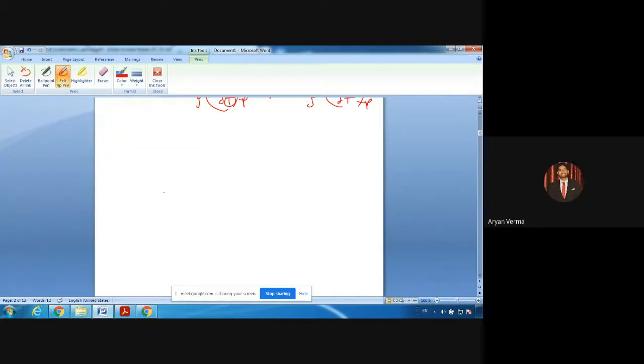सर, जब एक पाइप में आपका फ्लूइड फ्लो करता है तो जो शेयरिंग स्ट्रेस होता... Forget about the pipe. Forget about it. This is the development of the velocity. Yes, sir. If velocity is uniform throughout, meaning the same, no shear force, nothing, no hindrance at all, you will not find any boundary layer. Any layer will be developed there, because every layer has the same velocity, so there would be no shear stress.